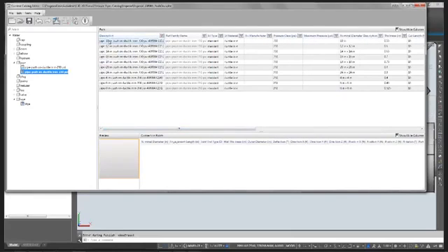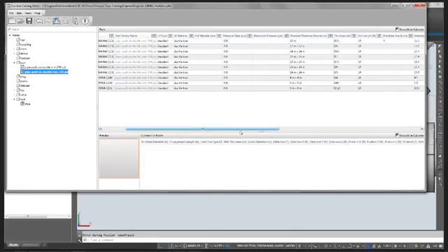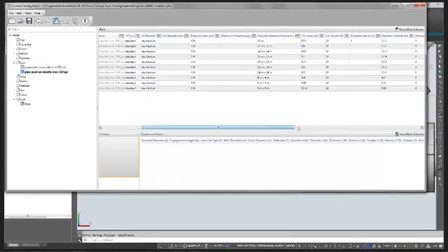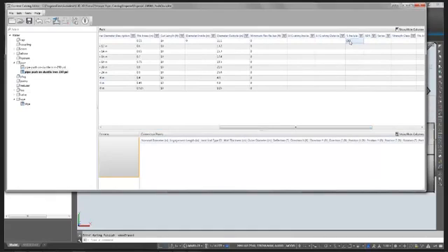Yep, right here, 10-inch pipe. I actually came in, and the first thing I did was the nominal diameter description. I just made it say 10-inch instead of 10-inch by 10-inch. It's a pipe. These values are confusing from my standpoint. So the first thing I did was come into my catalog and delete out the first part because I wanted it specified as 10-inch.